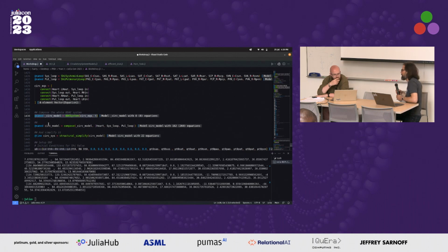So you could create that vector dynamically, and then there's basically no limit. Because you can create that first equation set in a function and then just export a dynamically created network model. Then you have a dynamically created component vector that goes into the second statement. So you can create arbitrarily complex models if you have a logical description of how the model is developed, like it's always a branch, or it's always a connection from this to this. Then you can dynamically create those, and there is no limit to the number of connections.